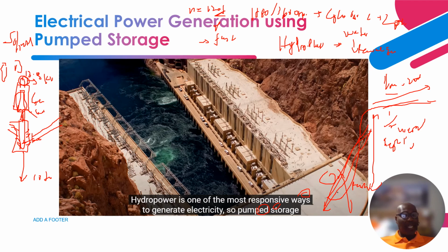Comparably, the salient pole machine that is utilized in hydro has a lot of poles. So let's say if you have a 100-pole machine, and you have a frequency of 60 hertz, the speed is very small. So that is why salient pole machines turn at a lower speed. Okay.